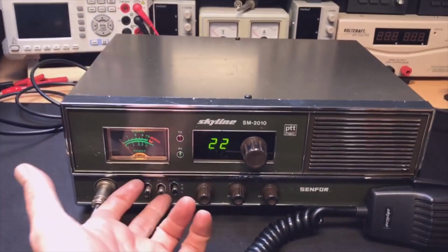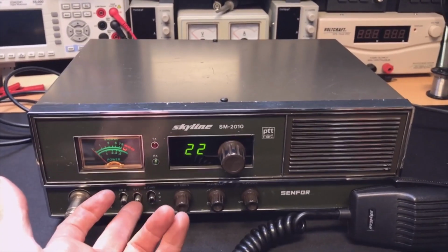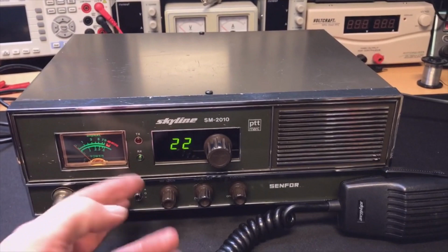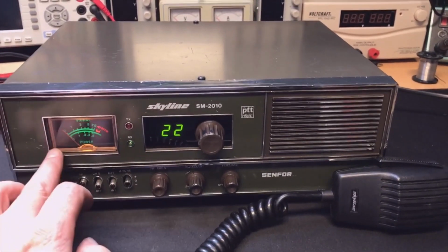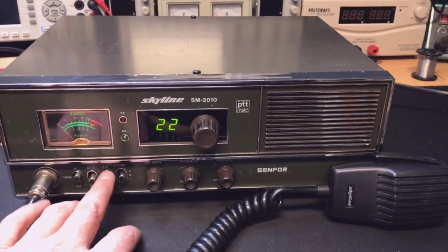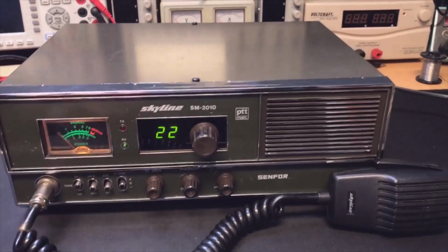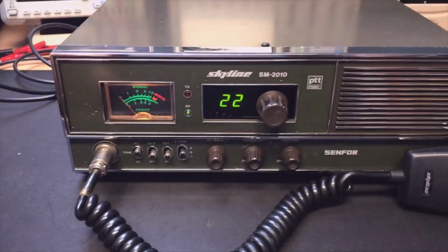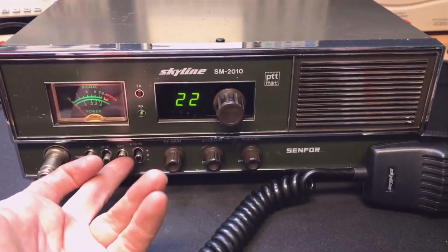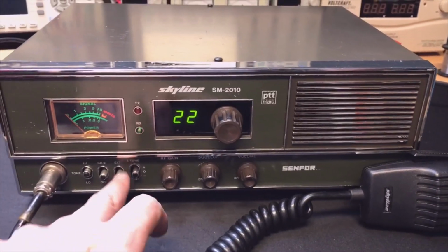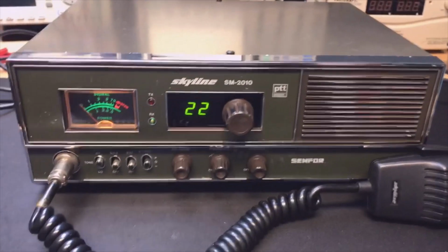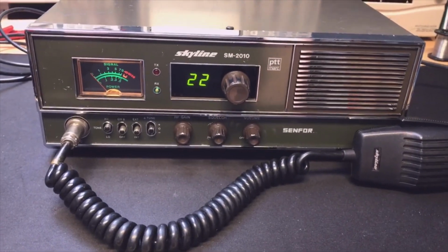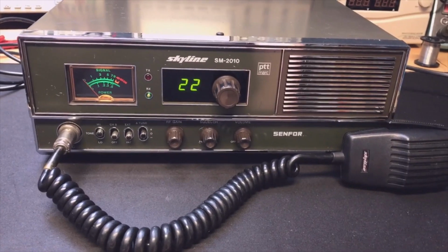You just need to remember, because you don't see anything in the display, sometimes people put a little LED light in the corner behind the S meter, so you can see it is actually on the 10 plus channel or on the alpha channel, or they put the light somewhere so you know, but now you really need to remember it was this switch. It is kind of a dirty trick with this variable capacitor, but it does work very well.